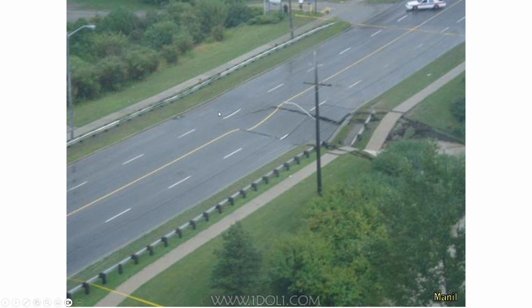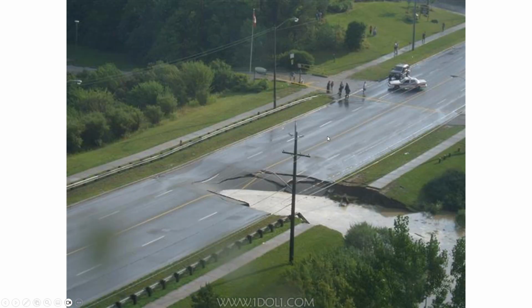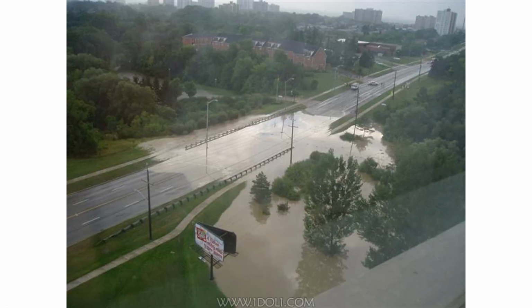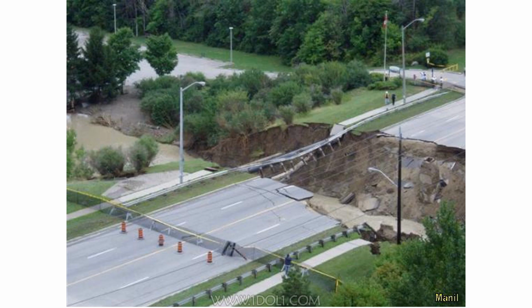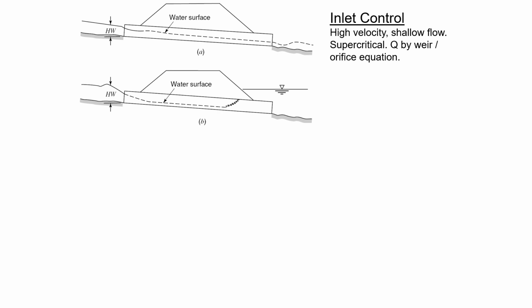The water carried some soil, enough of it that when the flow rates were high, then the entire road got demolished, the culvert floated away, and this is going to obviously take a little bit of time for them to repair. So that's kind of the stakes, is that if you have overtopping and you're not prepared for it, or if you have high headwaters and you're not prepared for it, then it can be pretty destructive and costly.